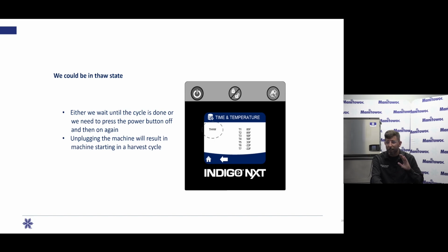The home screen, that's not for you and me, the technician. We need things like real-time data. Hey, look at this. We've been in thaw, not sure how long, but T1, which is measuring my liquid line temperature as it exits the condenser, is 85. T2, my compressor discharge line on a self-contained ice machine or traditional remote, is 85. And the evaporator on a single circuit, so inlet is T3, outlet is T4, are both sitting at 50. So yeah, we're not refrigerating, but it's because we're in thaw.